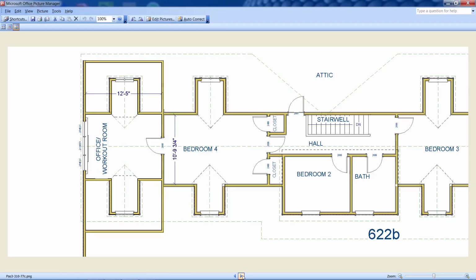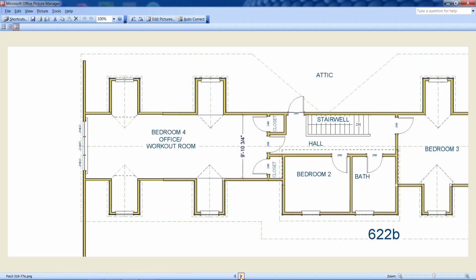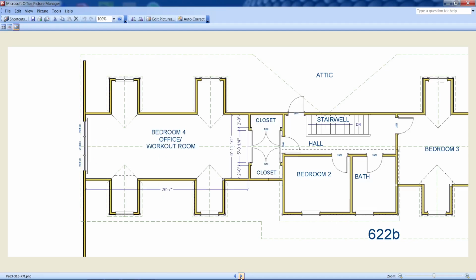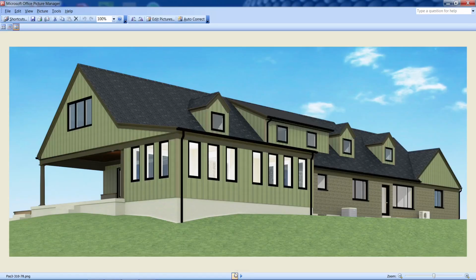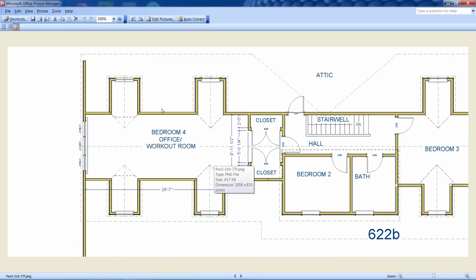That makes more sense if that's a truss design instead of stick framed, to just add a dormer on both sides. I don't know how big a deal this room is supposed to be, but if that's done, I think these walls need adjusted a little bit anyway, and I don't know what this dimension is, but it must be something close to this. If that's done, maybe that dividing wall is just taken out, and this becomes a much bigger multi-use room and has some real closets, and these are 56-inch wide double doors on each side, so quite a bit of closet space for bedroom 4. And it's a nice symmetrical layout as well. This is 26 long and there's 4 feet on each side of this.